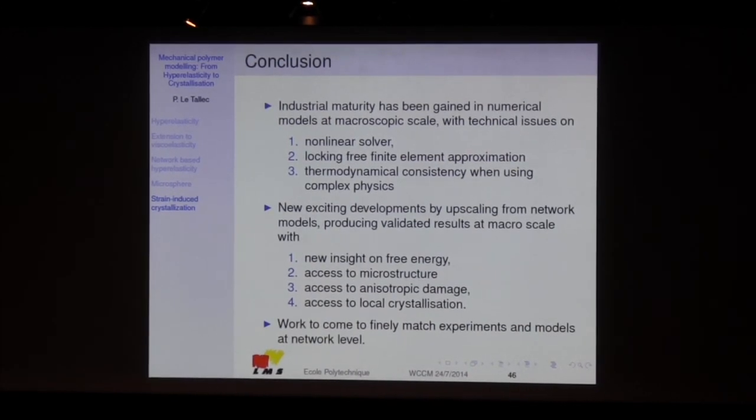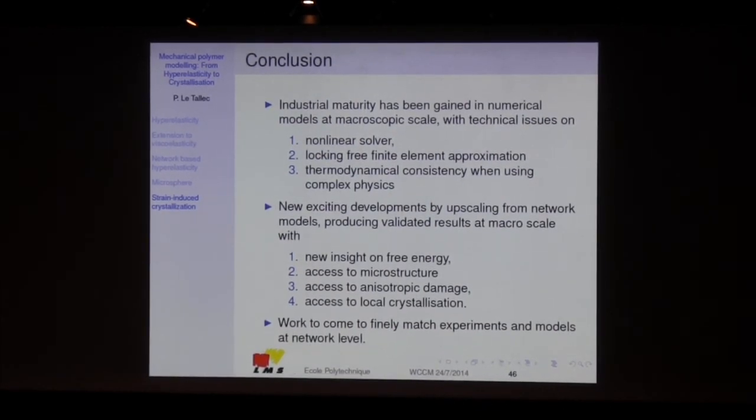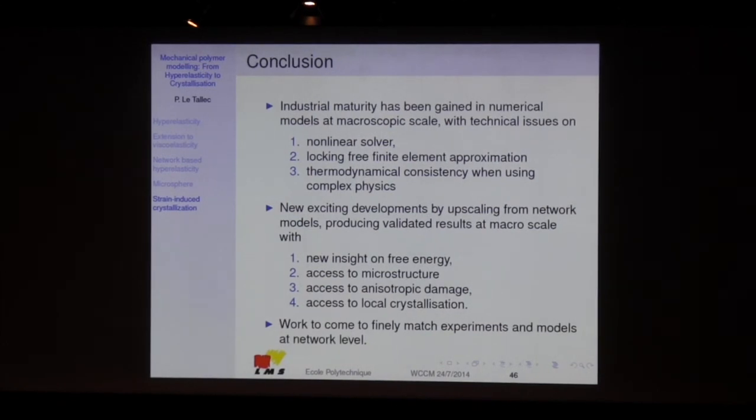You have stiffening. Well, experimentally, you can see stiffening, so because it stiffens, you have multiple branching. So the explanation is due to elastic stiffening, which will increase the G coefficient in the crack analysis. So the better fatigue properties are due to the elastic stiffening due to crystallization. So that's the end part of the curve that you must have.